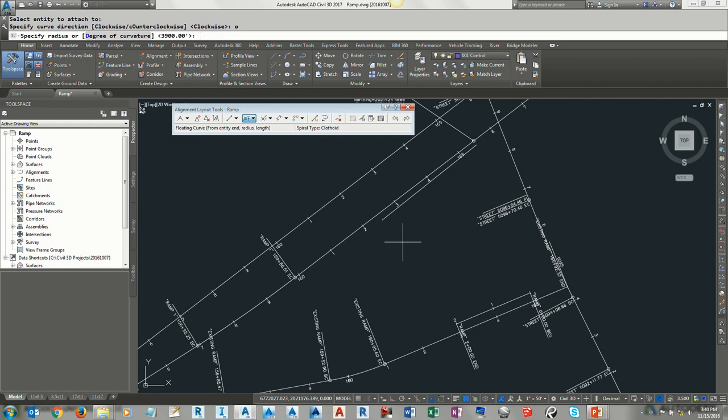Now, what I did not talk about or harp on is that on this template, I have the Caltrans XML file for design criteria, and that design criteria, reading on the speed that I have on this, which I didn't talk about, is giving me a curve radius 3900. But by default, the alignment starts with a higher speed. At that point, we do not have that full speed, so the curve radius at this point should be, based on their criteria, 3,000. So we'll go with 3,000 at that point. You can leave it at 3,900, come back and change it, but for now, we'll go with that.